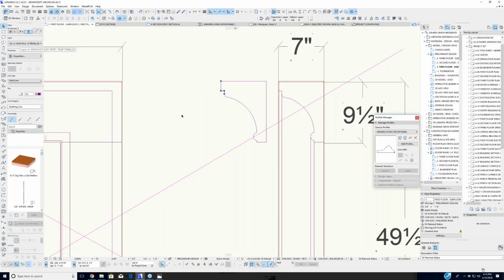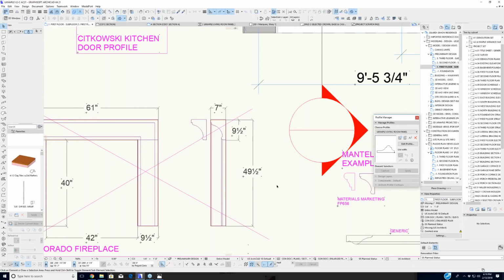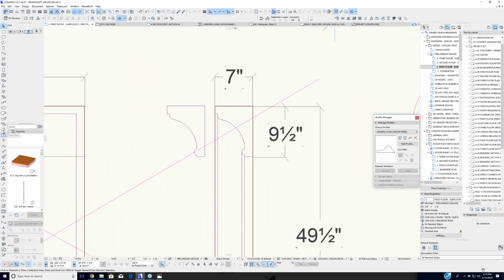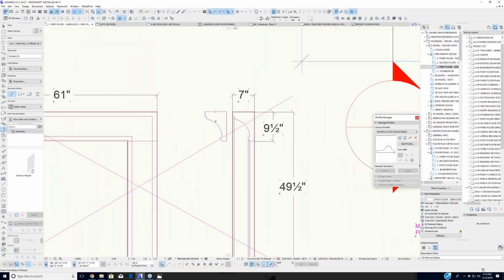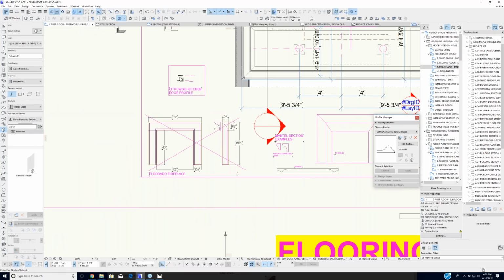On the non-plot layer, new, because this is part of the new. If I jump back for some reason, I need to go over to the existing floor plan. I don't want all this stuff to show up. This is now new, or it is a new mantle. So I will use the morph tool, space bar, and then when you click on that, it's going to give you a morph, and it's going to ask you what height. If I say 10 feet, I'm going to rotate it and drag those morphs around this, cut them just like you would real stone, and then eventually come up with something like this.